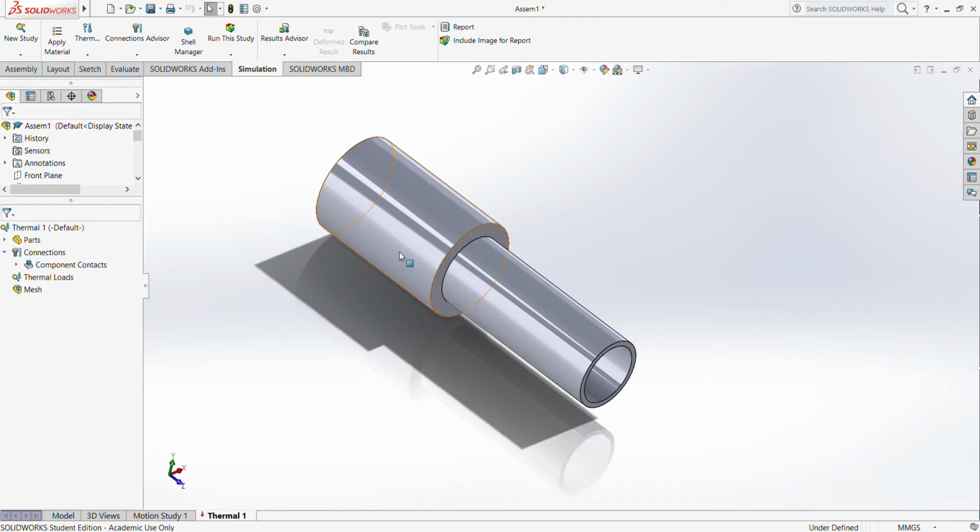Now the first thing you want to do is, where it says parts, you just follow the direction here. You're going to go from top to bottom. So actually, why don't we go to the very top where it says thermal 1. We're going to make sure we do a transient. Right now, SolidWorks will do a steady state as the default. But we don't want a steady state. We want to do a transient. We want to see temperature versus time. So we go ahead, like I said in the class, right-clicking symbols a lot of times gets you where you want to go.